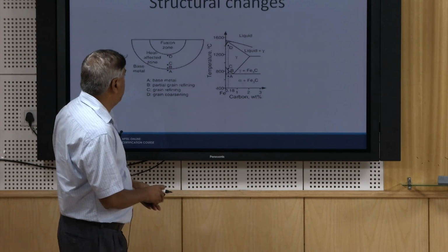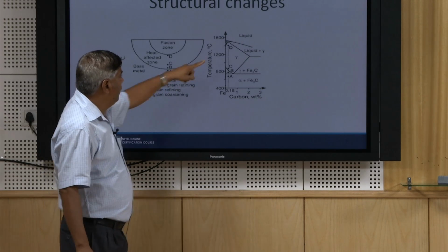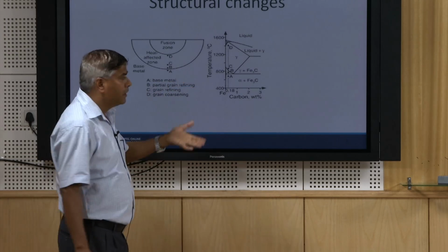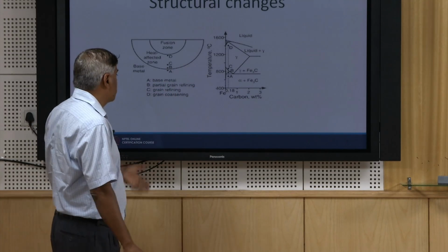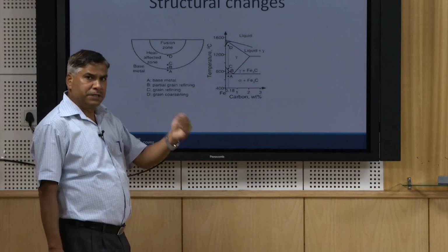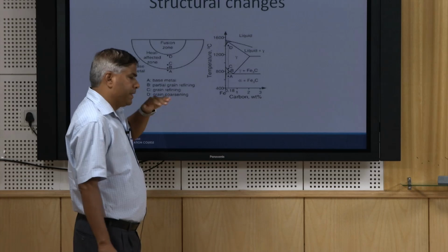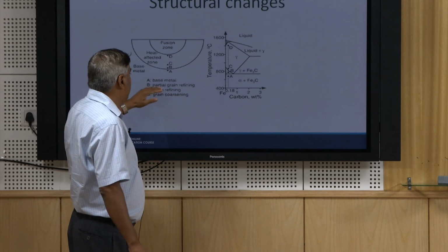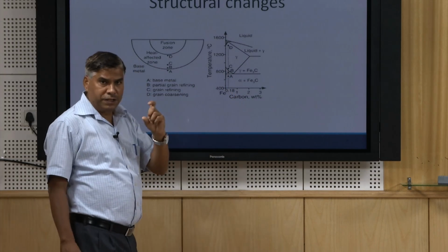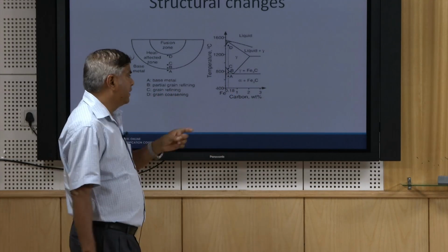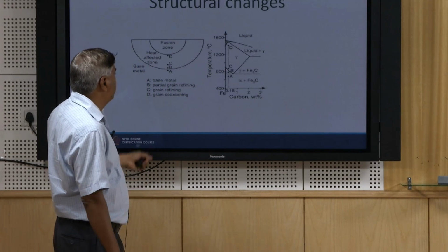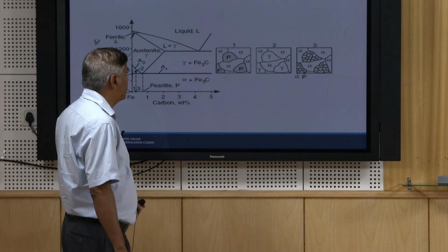So accordingly, point D will be experiencing grain coarsening in the form of austenite, and subsequent rapid cooling results in coarse martensite. C will be experiencing fine grain refinement, and this will result in fine pearlite, and a partially refined zone will be experienced by point B, which is in the two phase zone. Basically it is the intercritical zone falling between the upper critical and the lower critical temperature lines, and the base metal is A.